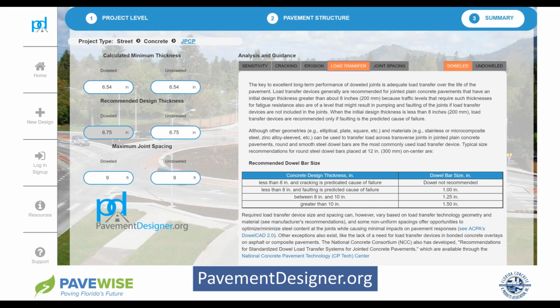However, since we're in Florida and you look at what the DOT says, they have a little table, I think it's called the 350-001 series, on the 4th page. There they even discuss if you have 6-inch thick pavement that you can put a smaller size bar than 1 inch. But then the rest is about the same as the DOT. So real interesting information there.